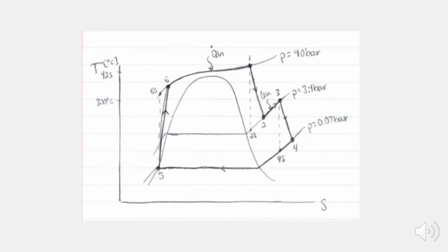This is the TS diagram for our Rankine cycle. Since the project description limits the maximum pressure of the cycle to 16 megapascals, we chose to use ammonia as our working fluid. Choosing ammonia as our working fluid, the top isobar is above the vapor dome and supercritical. This provides advantages since thermal efficiency is correlated with a higher temperature and pressure.